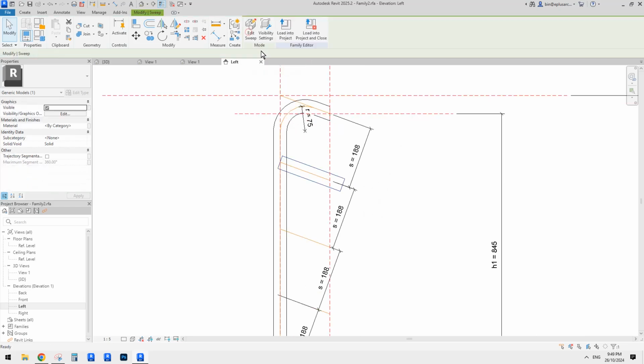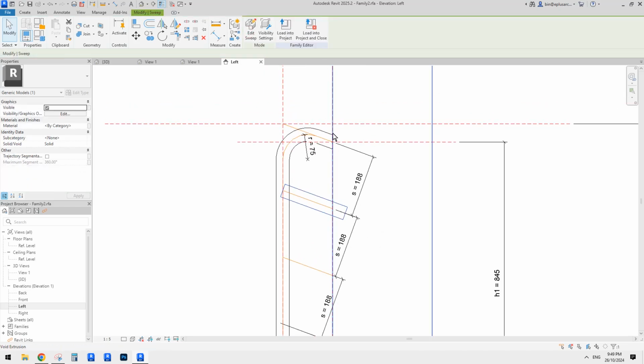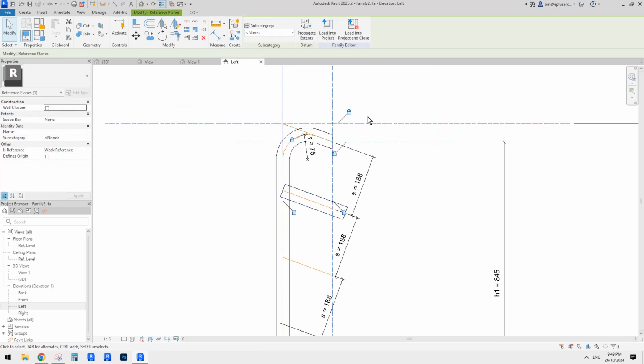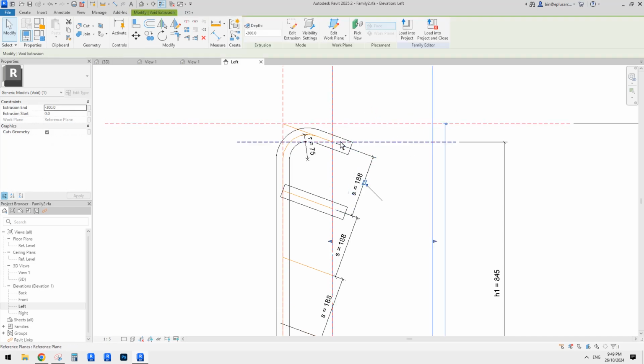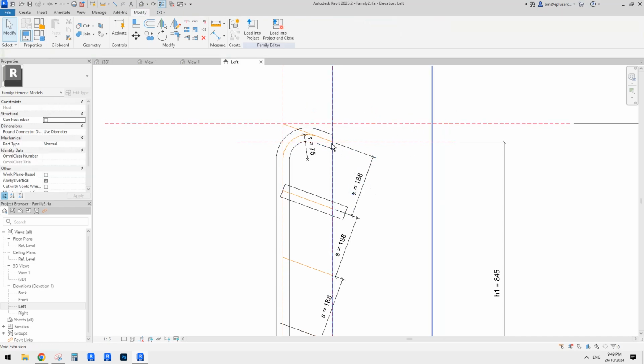Because we still have a void, you can pick this void by moving your cursor around here, around where we cut this solid. Then cut geometry, pick this one, move your cursor around here and cut. This will also cut this bit.